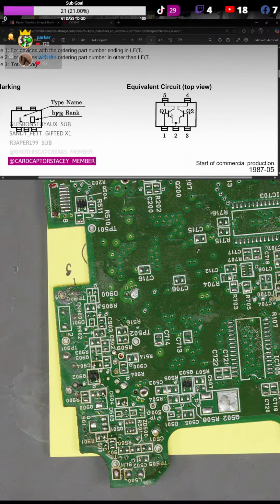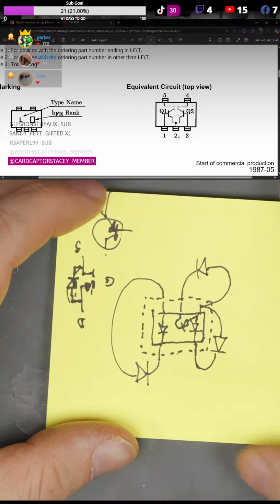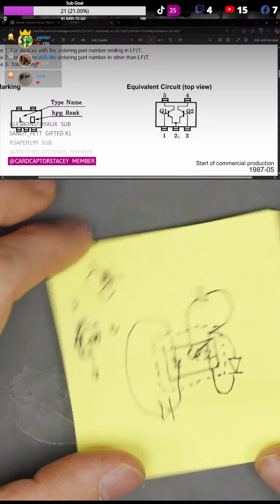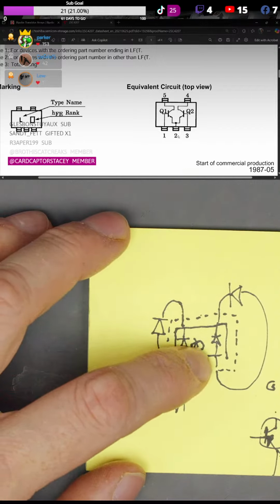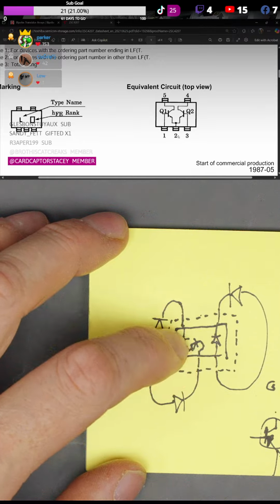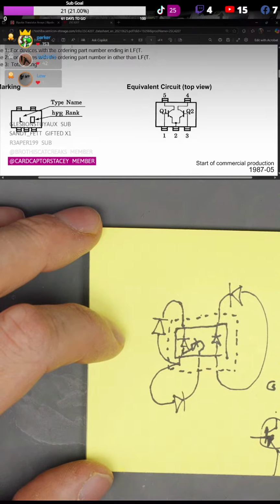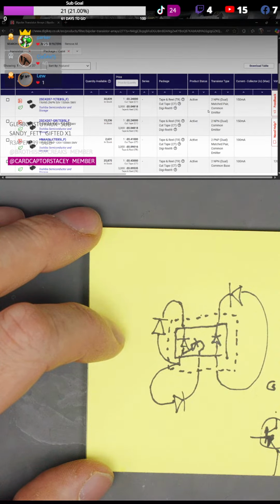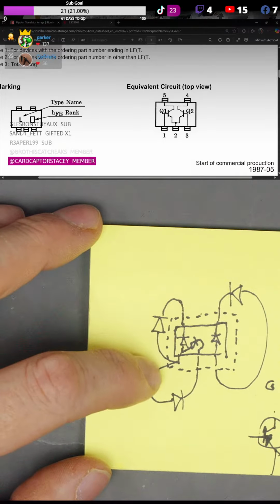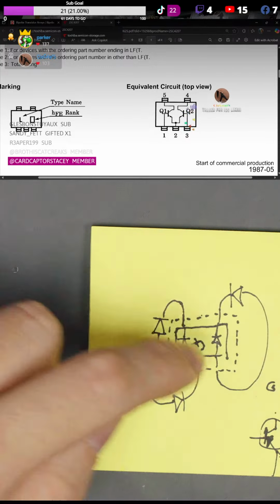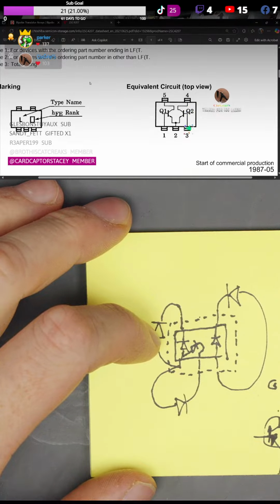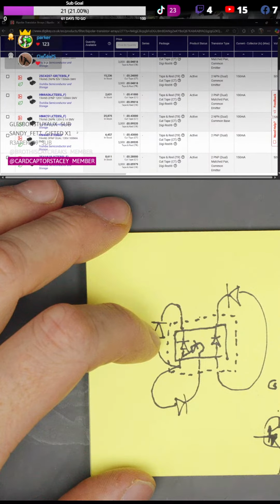Pin 2 and 3. All right, so let's look at this again. That's the orientation most data sheets are in. There'll be a diode flowing this way, which there isn't, because that's going to be a base, so it's not going to be that one straight away. So it's not a 2 NPN dual match pair. Let's try a common emitter. Now, the thing is, we've got one common, and the others aren't common. This almost seems isolated. This is going to be strange to figure out.